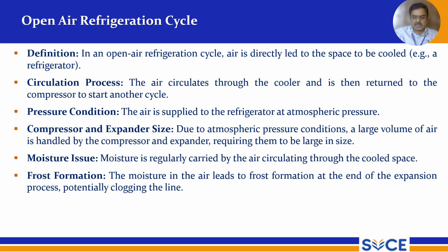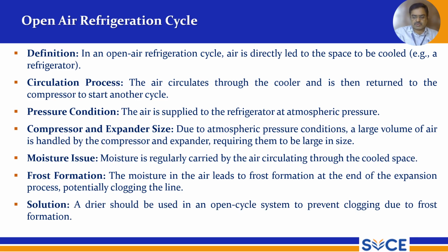Solution we can provide: a dryer should be used in the open cycle system to prevent clogging due to frost formation. So we can use a dryer. Once we use a dryer, it will dry out the frost, the frost is actually melted, and that will be taken out of the system.